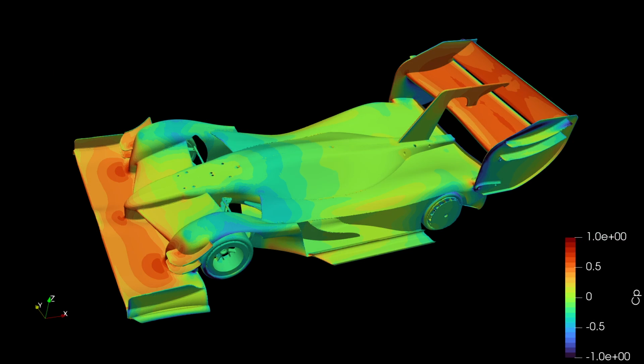The one topic that always comes up when you're talking about CFD is, are the numbers coming from the CFD simulation absolutely accurate to the real world? And no, but they're very close for most circumstances. CFD is excellent for doing back-to-back comparisons in a controlled environment between different design choices, visualizing the interaction of different aero devices, and even aero balancing the car. While CFD is not perfectly accurate, it's orders of magnitude more accurate than human intuition will ever be.